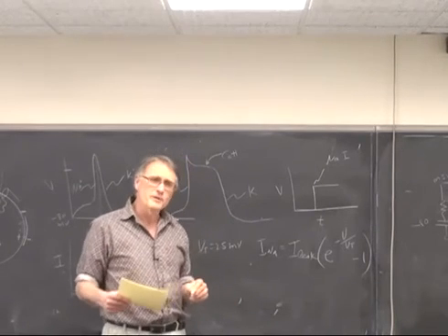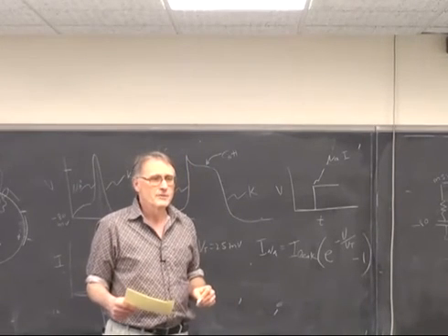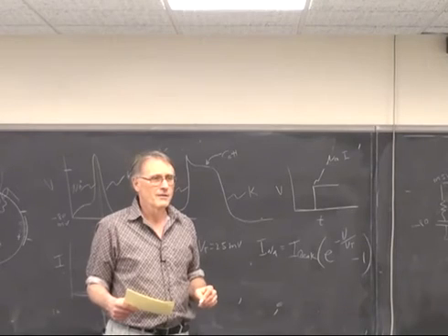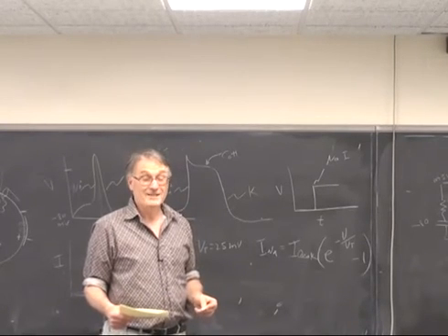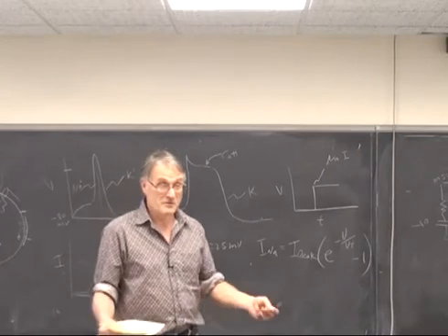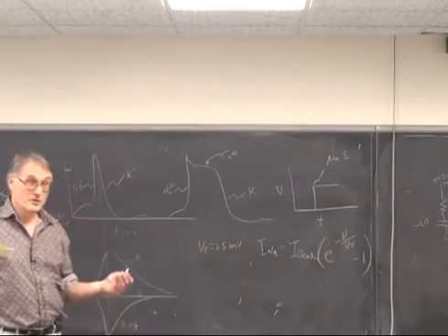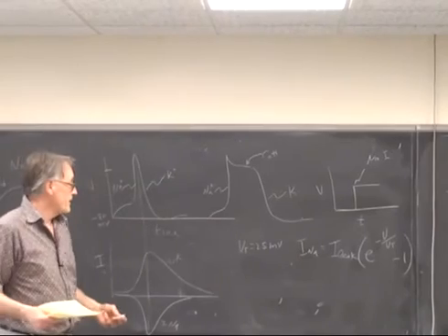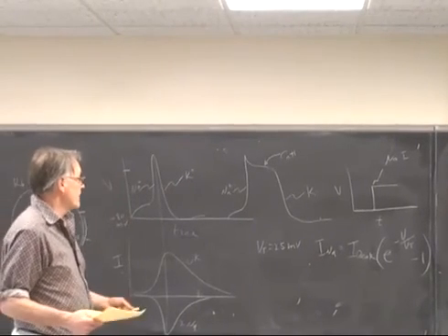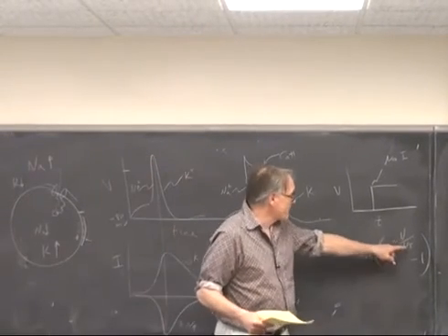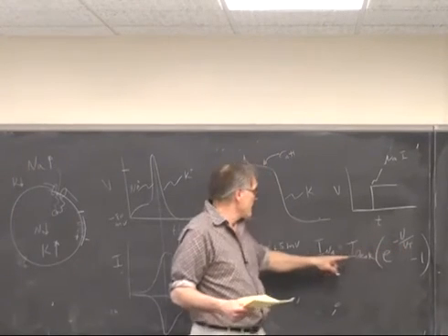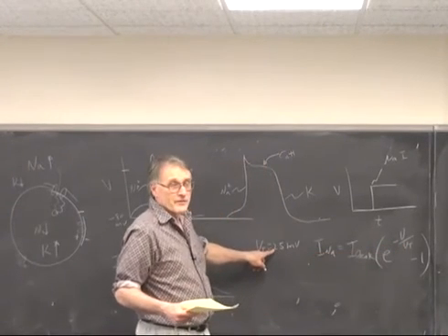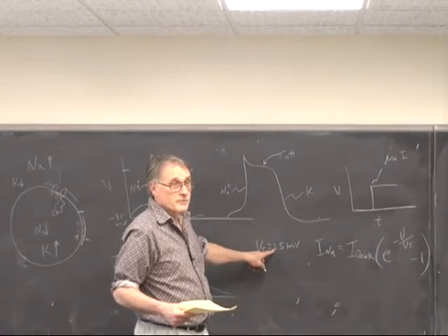Does that look familiar to anybody? What does that look like? Looks like a diode. Looks like a PN junction. For exactly the same reason. It's a Boltzmann activation from a voltage relative to some kT. Right? VT is kT. It's about 25 millivolts at room temperature.